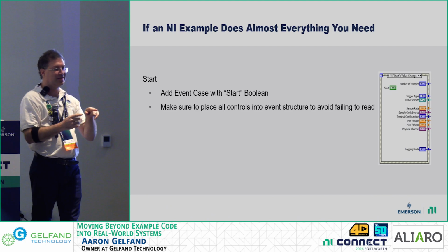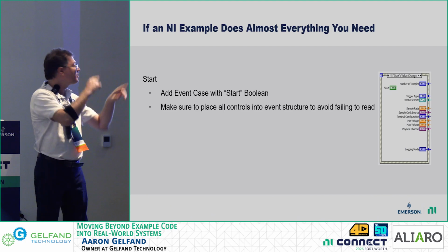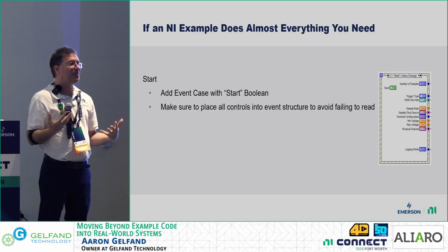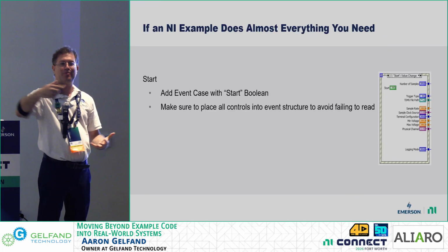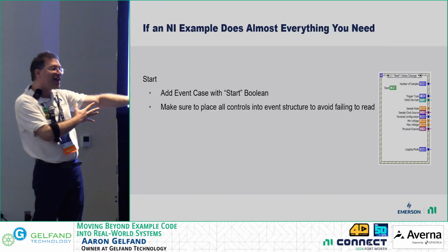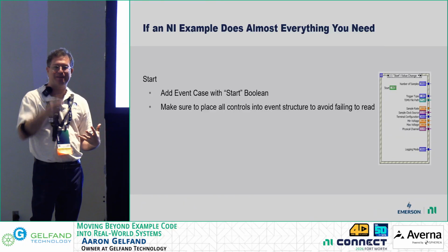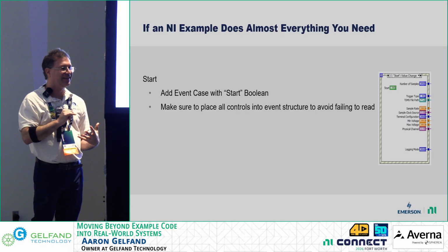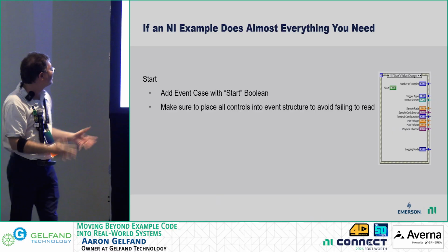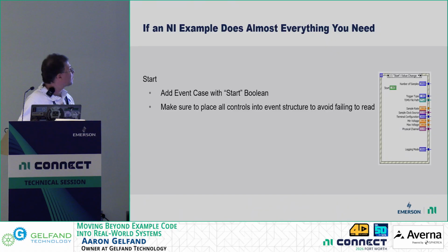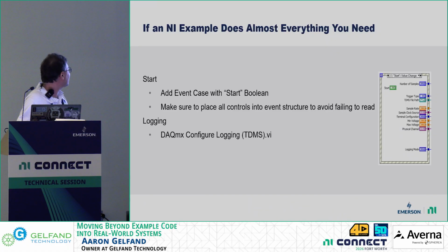And so we see we have a start button, we have all of our controls, because if I just do a start button and my controls aren't inside that event structure, what's going to happen? LabVIEW is going to open, it's going to read all these controls. It might be waiting on the start button, but you've already read everything, so any user interaction of changing your settings is ignored because LabVIEW already read it. We want to make sure to place all of our controls inside to avoid that error.